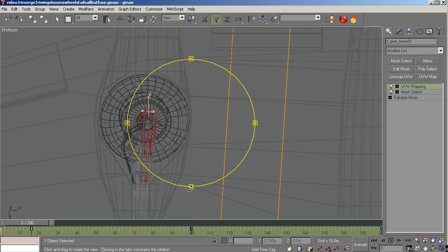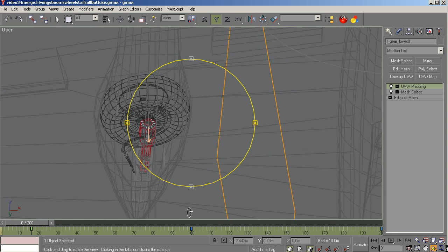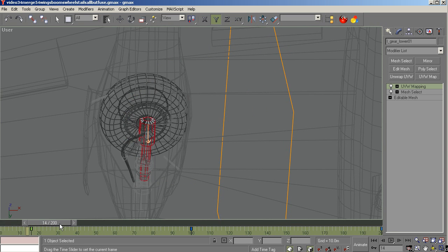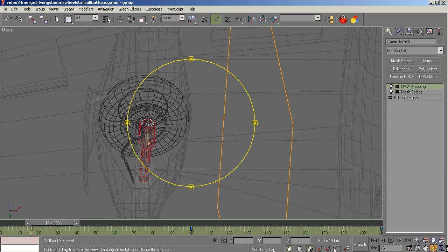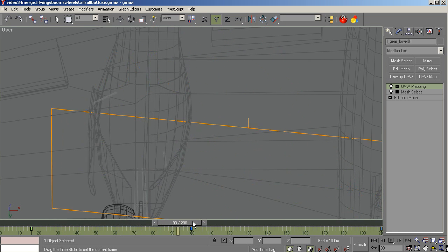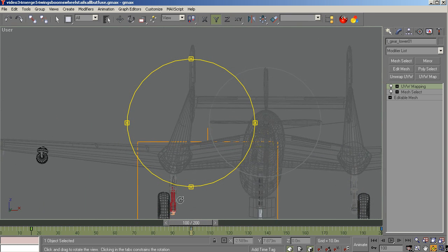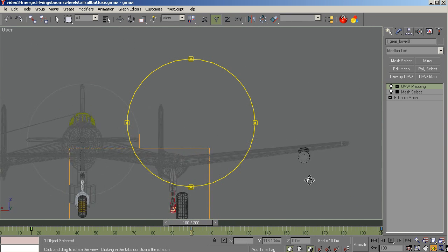So once you get that positioned in there correctly and ready to animate, all you have to do is add this keyframe here and go to this position and click on the Animate, and then go ahead and let your main gear rotate down on the upper gear, and then reposition the wheel so that it's pointing straight ahead back to its original.